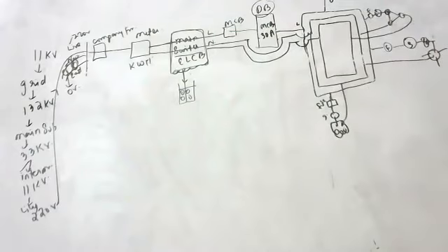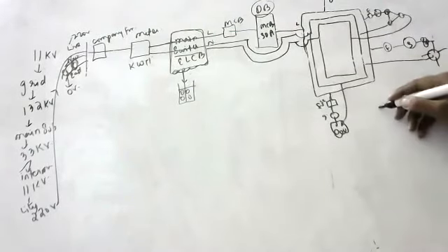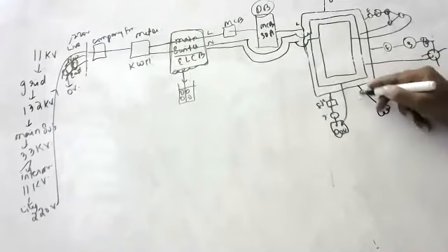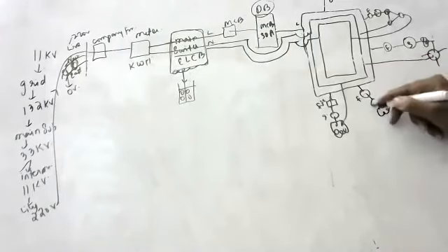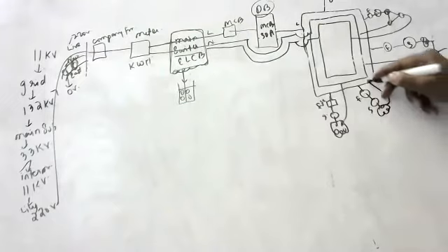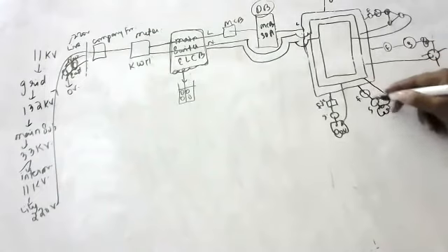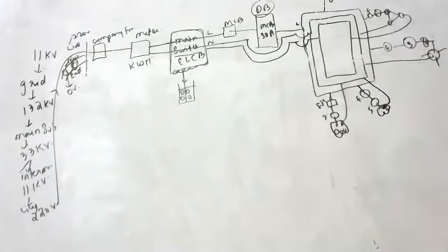Those who didn't understand, once again, one more lamp I will show. One more bulb is there. One live wire connection will have one fuse and one switch. And the other terminal is connected to the neutral wire. The live wire will have a fuse and switch because it is the one bringing current. The other terminal is connected to the neutral wire. Children, this is the ring system of connection.